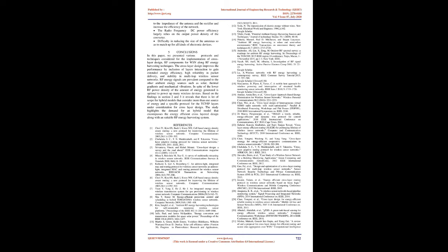Wang et al., 2015, proposed a design for RF energy harvesting using an enhanced full-wave CMOS rectifying charge pump. They have used body-connected PMOS diodes for rectification and switching for capacitor charging pump with a low voltage operation of 0.4 V. Lin et al., 2017,